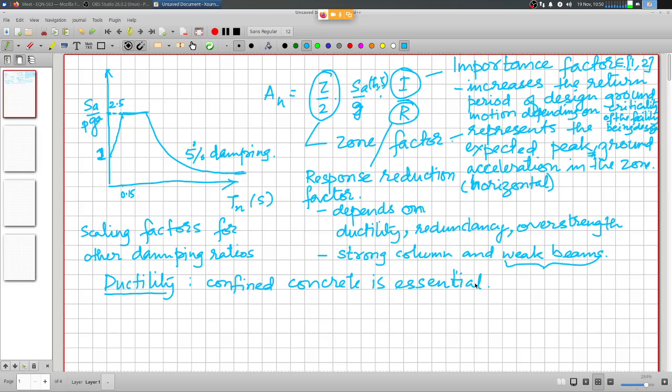So eventually you will find that if the concrete is not properly confined and the unconfined crushing strength governs, then there is not much ductility, irrespective of the amount of steel that you put in. So concrete has to be able to withstand much larger strain before you can harness the large yield plateau of steel elongation in the ductile behavior.